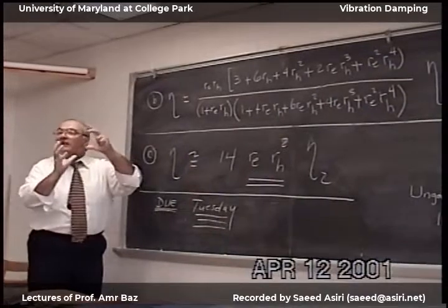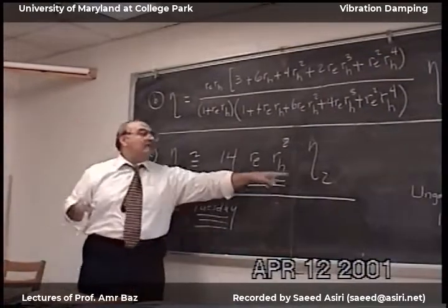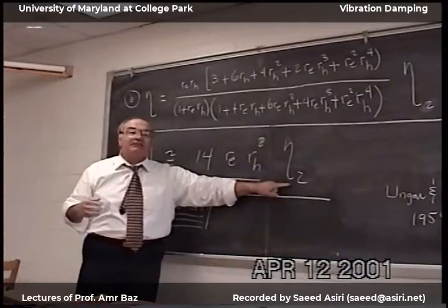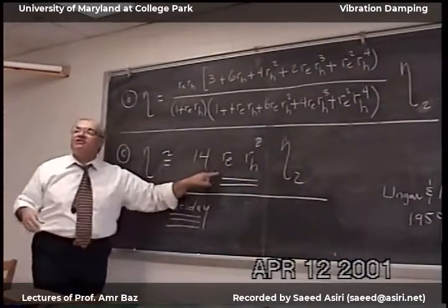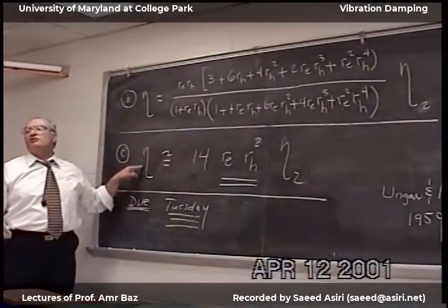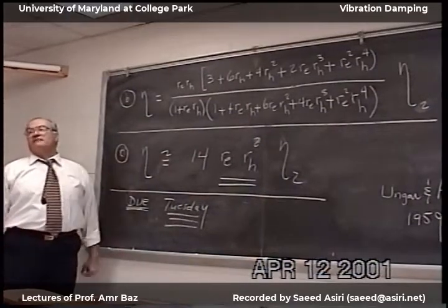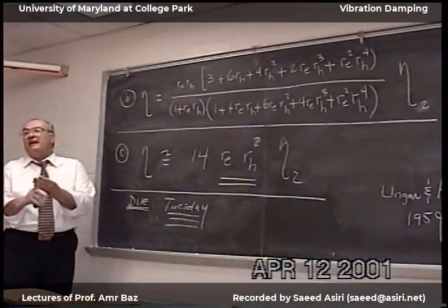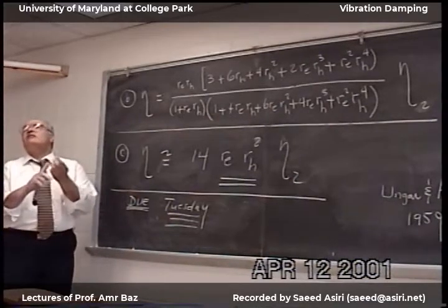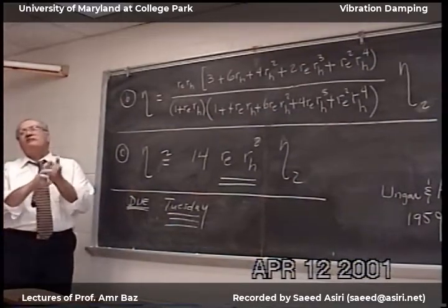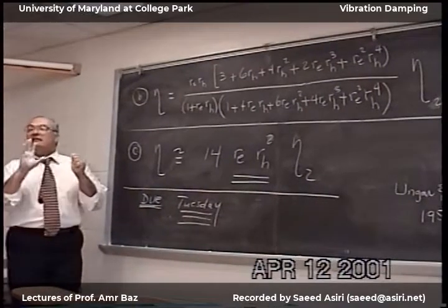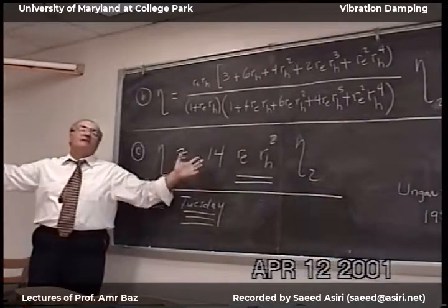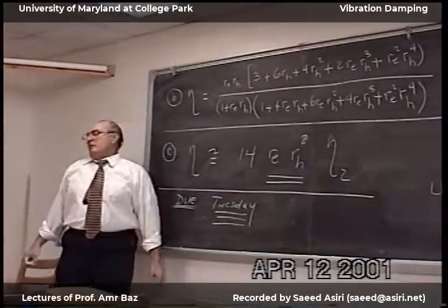They look at the total energy, the number that you give them to designate the viscoelastic material, they take this number, multiply times this ratio, and then give you the modal damping ratio for your case. No commercial finite element package has any of the GHM, ATF, or any one of these models. And the only method that they use is very similar to this very simple case. Okay.